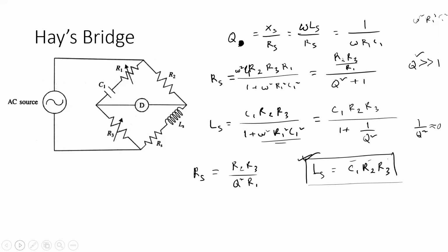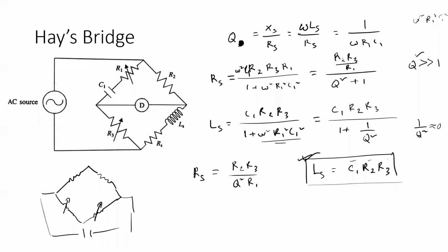Even in case of DC bridge circuit, suppose there are 4 resistive arms. Normally what we do, we vary only one, right? But what if we want to vary 2 resistors? Suppose 2 are fixed, but for some reason we need to vary both R and S to obtain the null point. So that would be difficult to obtain, right? I mean, varying both R and S, tuning them at a point where we are getting the null deflection. Yes, sir.